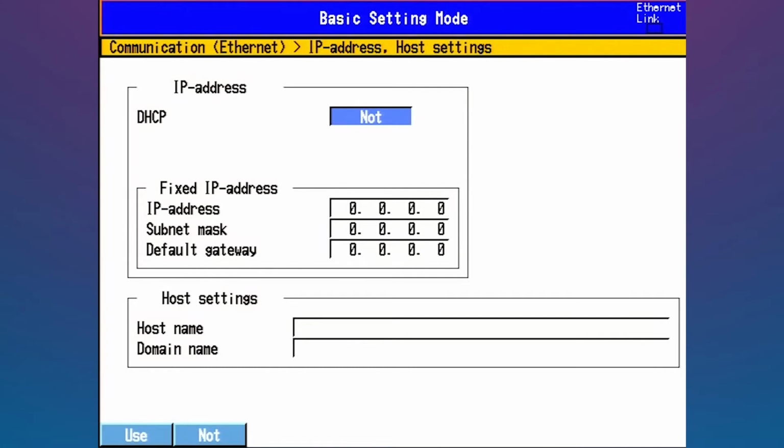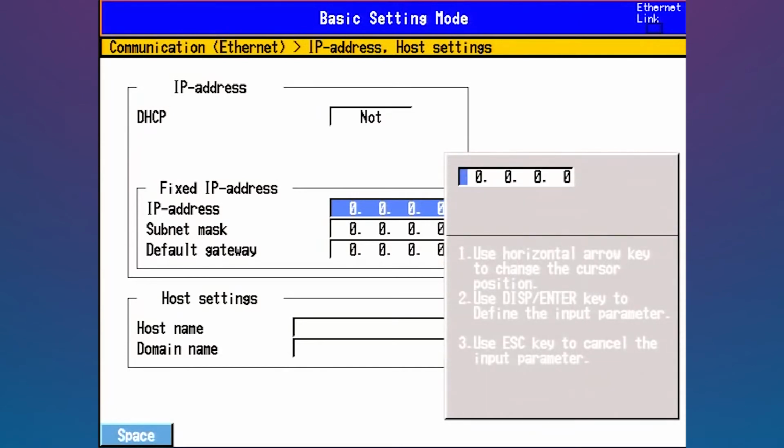Well, if the recorder is still working otherwise, you can always come in through the Ethernet and view pages via the web interface. You can configure the unit via software, stuff like that. It's just really good to have an IP address in it, just in case you need to get into it for emergency purposes over the network. All right? And then essentially to do that, you just go down here, you put in your input, go ahead, put in whatever IP address you want. So I'm just going to put in this as my default address.